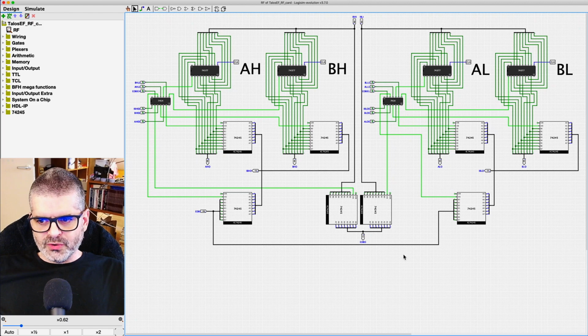In the next episode, we are going to, like we did before, grow this model here into a test bed. The test bed model you cannot use in the hierarchy of simulations. You cannot use that as a little box in the simulation of Talos, because it will have all kinds of other things that only have meaning in the final hardware, like the LEDs or the dip switches to control these control signals here in a standalone mode when you're not using that card in connection with the rest of the system.